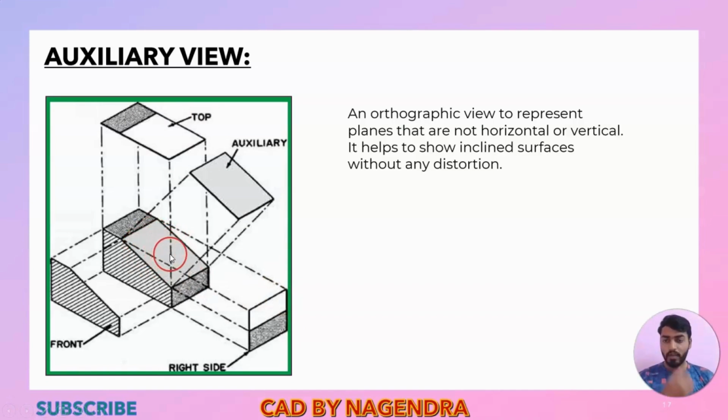Usually whenever we have flat faces, we get all the views properly, but when we have inclined faces, whatever true shape lies on that inclined face, we will not be able to see properly from either the front view, top view or side view. So in such cases, by using auxiliary views, we are able to get the true shape which lies on that inclined face. We take the projection of that inclined face and specify it separately. This type of view we call auxiliary views.